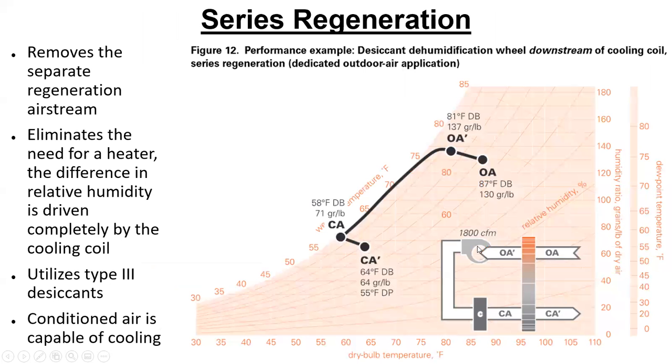Kind of interesting, and that was true; I should have said that over here on this one. All this moisture that's taken out on regen stays in the system, and it comes down and hits this cooling coil. That's one reason that cooling coil is colder, so we can condense that out, and then we just trim the moisture level down a little bit more with the desiccant.